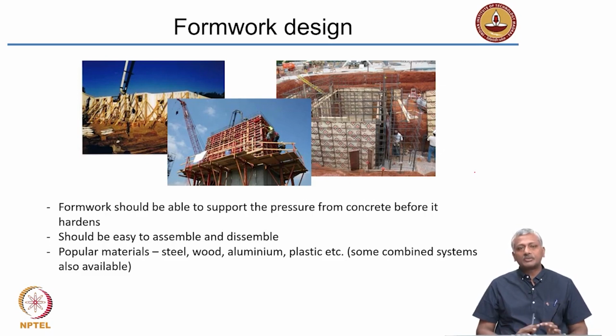We don't really worry too much about curved sections, but indeed there are several examples of construction where curved sections are also used. So in such cases, you need to design the formwork appropriately with the right blend of materials. Okay, there are different formwork materials. In most of the job sites, you may see that the formwork materials are made out of plywood or other pieces of timber. So in such cases, of course, you can imagine that the reuse is going to be limited when you use timber formwork, for instance.